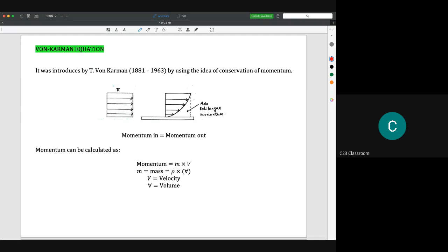And then, as I mentioned previously, we aim to get the drag force and the lift force, or at least we need to know the value of shear stress, because only the shear stress is difficult to get from measurement. So we need to find the value of shear stress, the tau, because we want to substitute it in the equation to find the lift and the drag force.